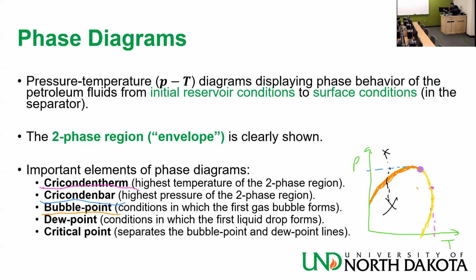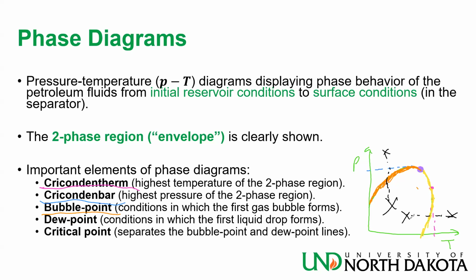Now let's go here. I have high temperature, certain pressure, and I move here. Same pressure, lower temperature. What happens? So from vapor state to mixture state. Yeah, two phases. Yeah, that's when the first liquid drop comes out of solution. We call that the dew point. And between those two lines, we have the critical point. Now, that critical point was with purple, right? There you go. So those lines that we saw, they have a certain